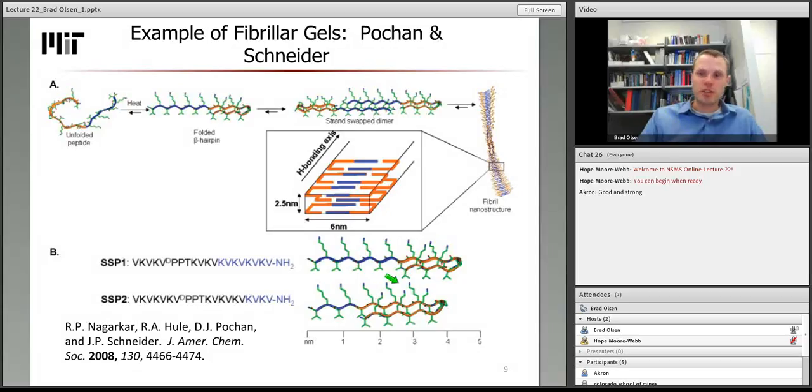They're formed in general by relatively small molecules, and so they form fibers of narrow dimension, but the fibers will self-assemble rapidly in one dimension in order to form a highly extended aggregate in that dimension, even as they stay small in the other dimensions. So I think one of the qualitative recipes for being able to self-assemble these types of fibrillar structures and fibrillar gels is finding things that self-assemble in a limited dimension in 1 or 2 dimensions, so that they self-limit their dimensionality, but that grow into very long structures in 1 dimension. A one-dimensional growth or crystallization process is one way to envision what's happening in these types of structures.